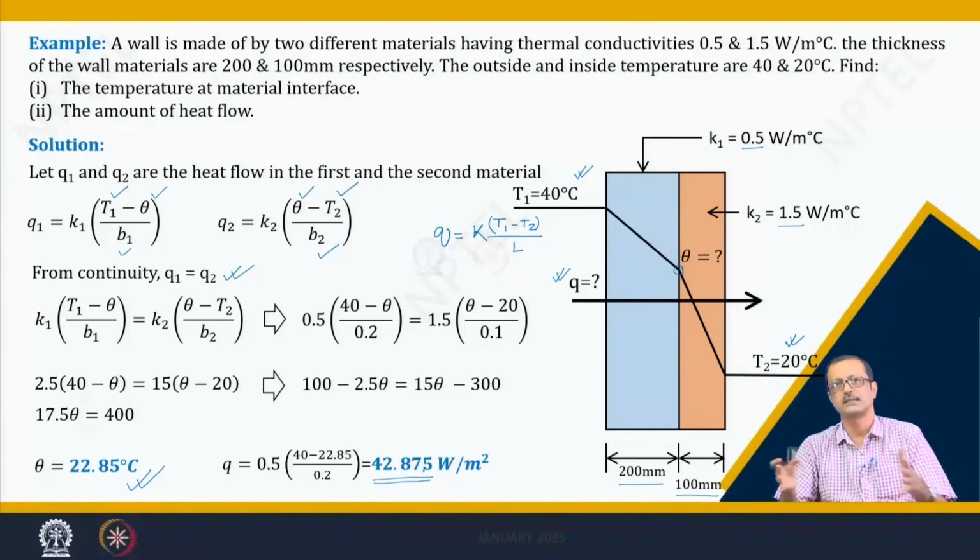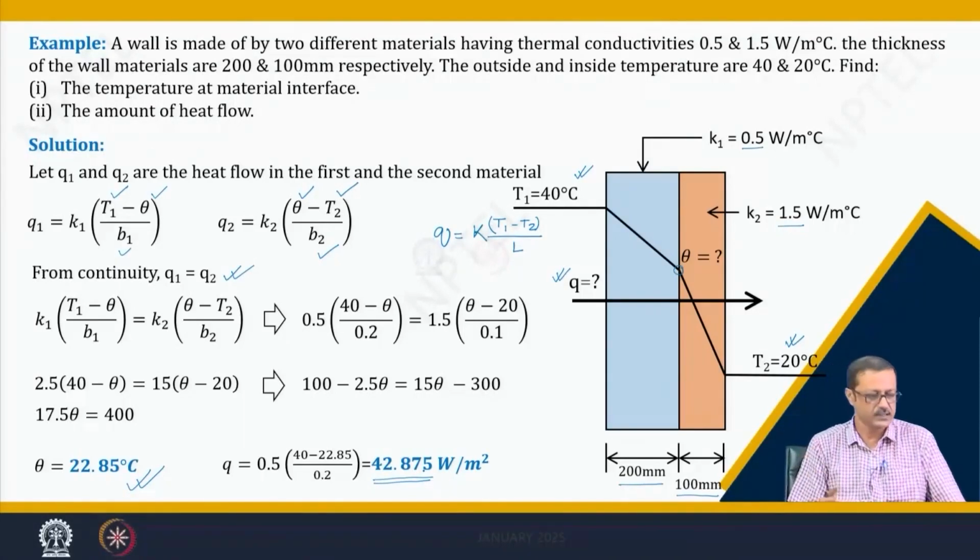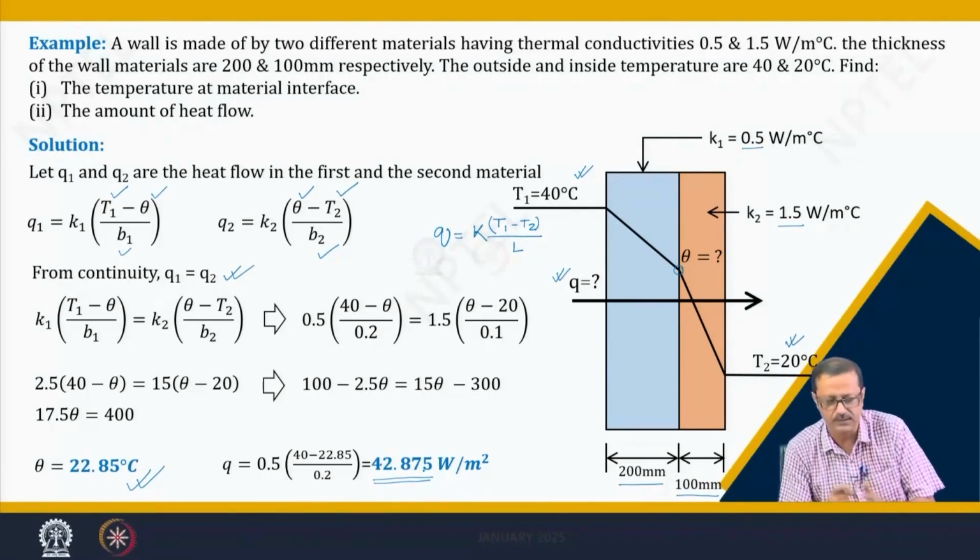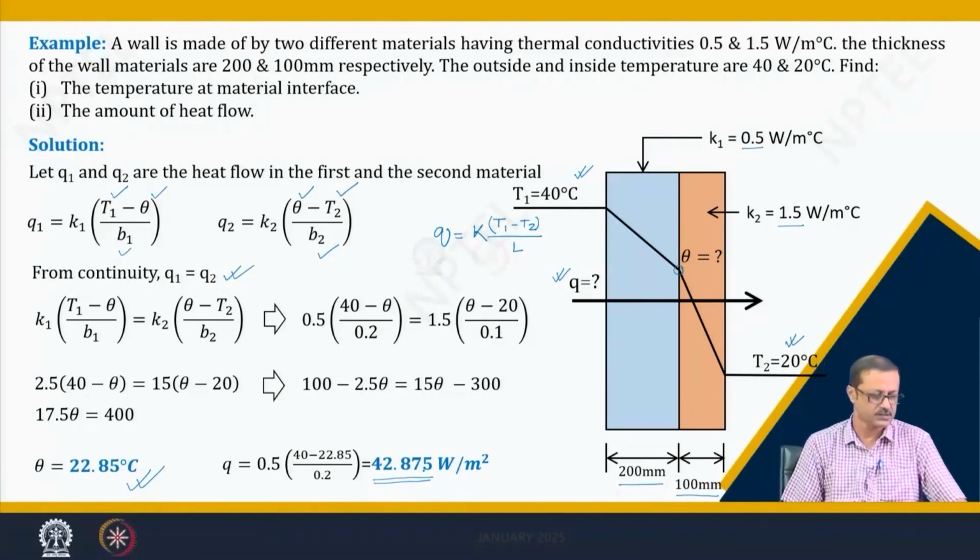Now, in reality, in the building envelope, or in the roof or the floors, we have 2-3 different types of material. We may have a brick layer, and we must have at minimum some plaster, or maybe a cavity wall, or in the roof we may have an RCC roof and over that some protective waterproofing layer. So there are 2-3 layers of material with different K values, and it should be analysed in this way.